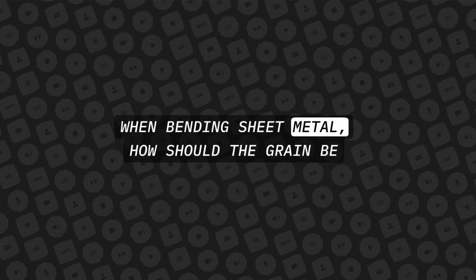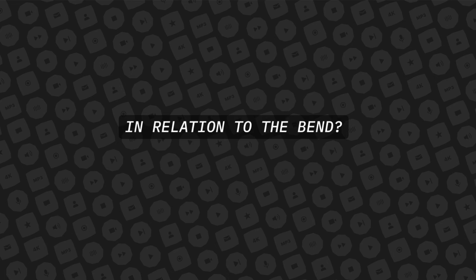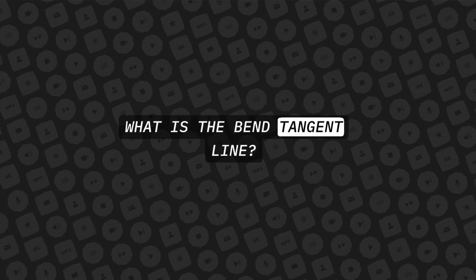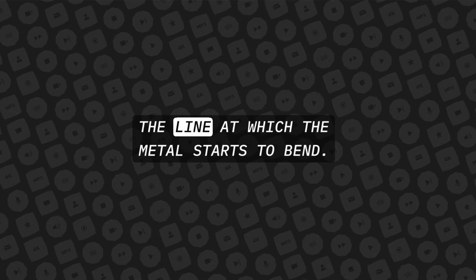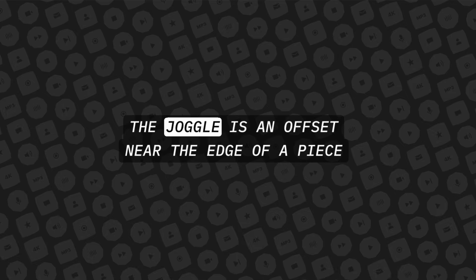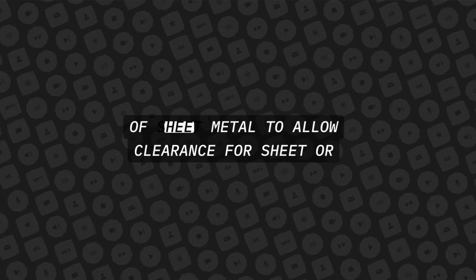When bending sheet metal, how should the grain be in relation to the bend? The grain should be perpendicular to the bend. What is a bend tangent line? The line at which the metal starts to bend. What is a joggle? A joggle is an offset near the edge of a piece of sheet metal to allow clearance for sheet or extrusion.